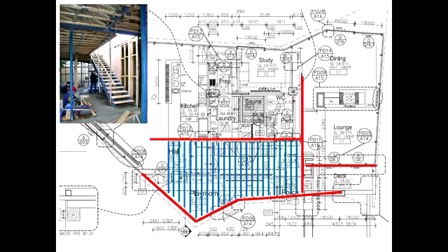In this case, it's a bit more complicated, because I need to make sure that I have a trimmer, and I make sure that those two joists are a little bit stronger to make sure that the structural continuity is restored.